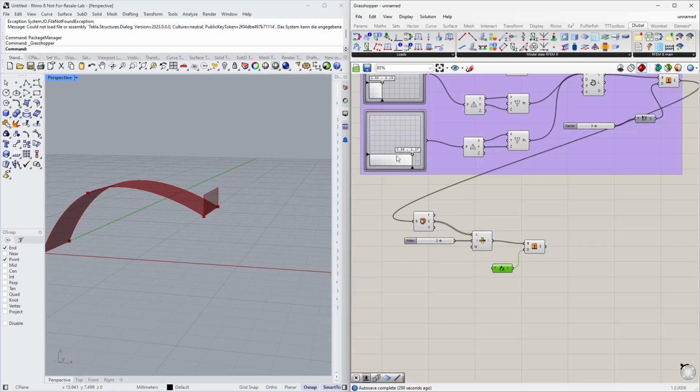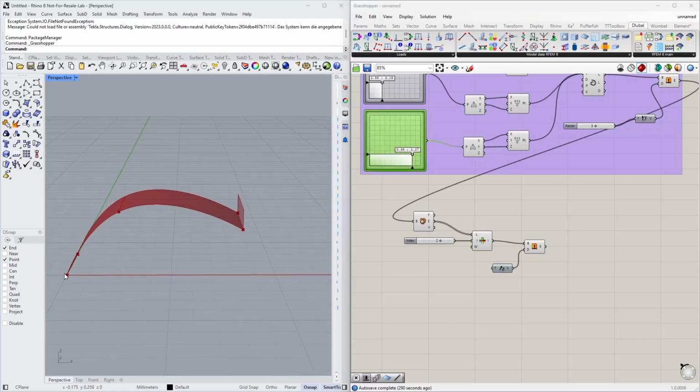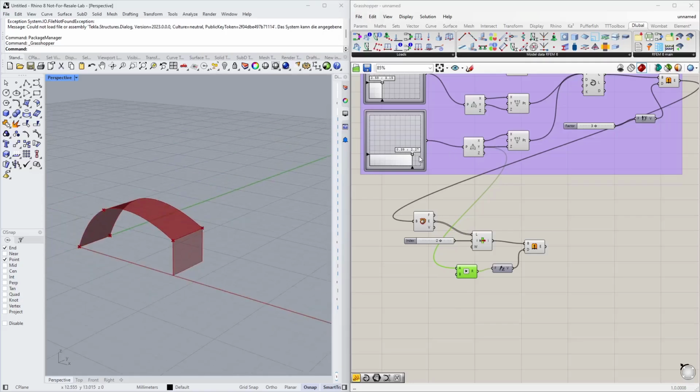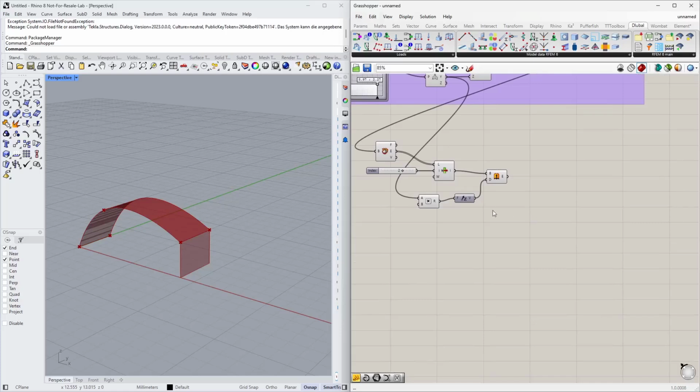And the coordinate itself comes from my arc or my curve that I defined in the beginning. It's the Z component or Z coordinate of that node. So obviously the Z coordinate here, and multiplied by -1. So we make a little multiplication component, and then it always has the right height. Yeah, so even if I play with my slider, the wall always gets the right height at the end of the day. All right, that's the first part.